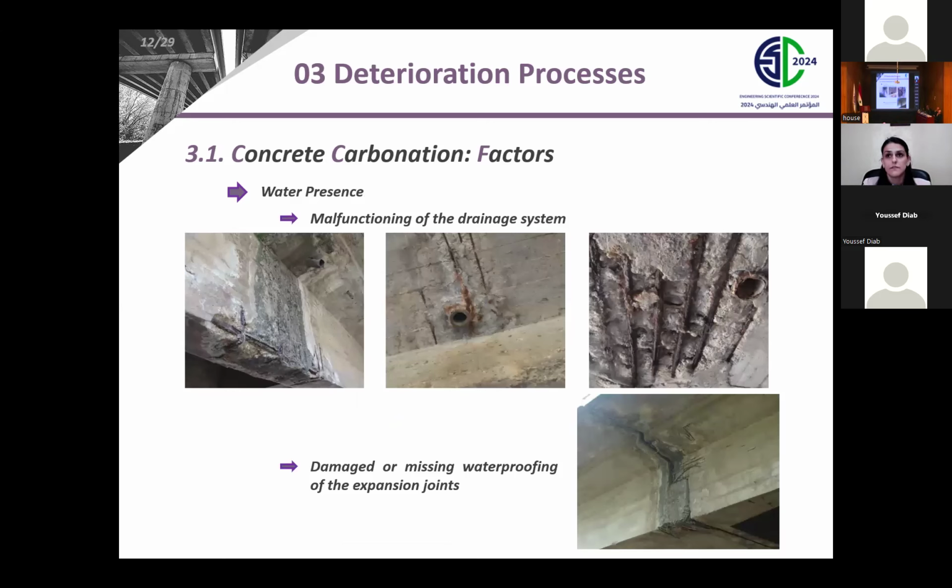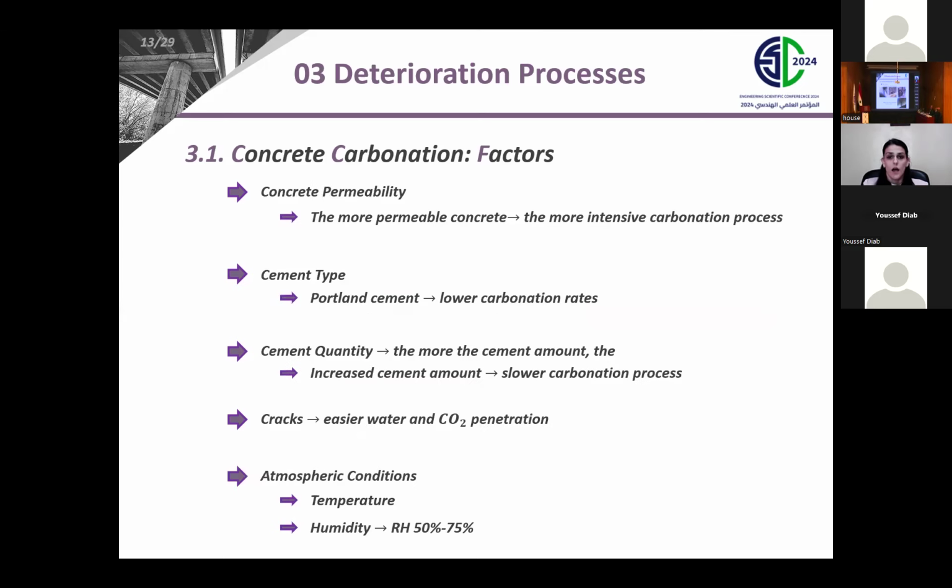Another factor that affects the carbonation progression is the presence of water. It is an important part of the carbonation process as it provides the environment in which the chemical reactions take place. Water exposure is usually due to malfunctioning of the bridge drainage system or damage or overall missing waterproofing of the expansion joints. Other factors affecting the process of carbonation include concrete permeability, the type of cement used in concrete and its content, the presence of cracks, and atmospheric conditions such as temperature and humidity.